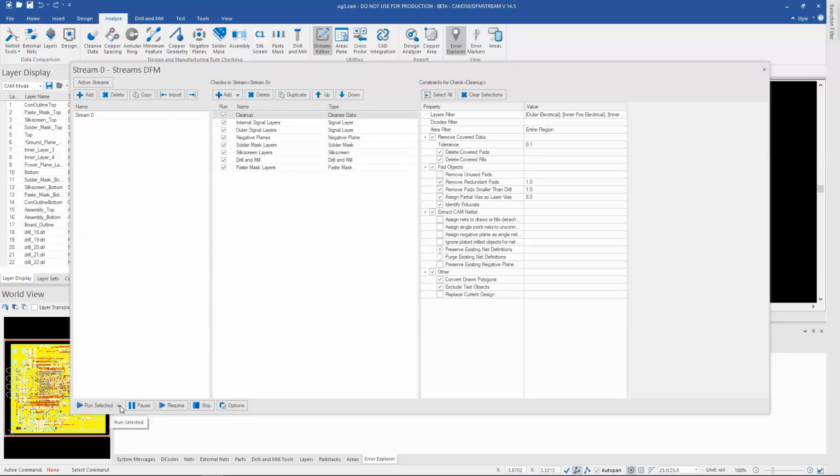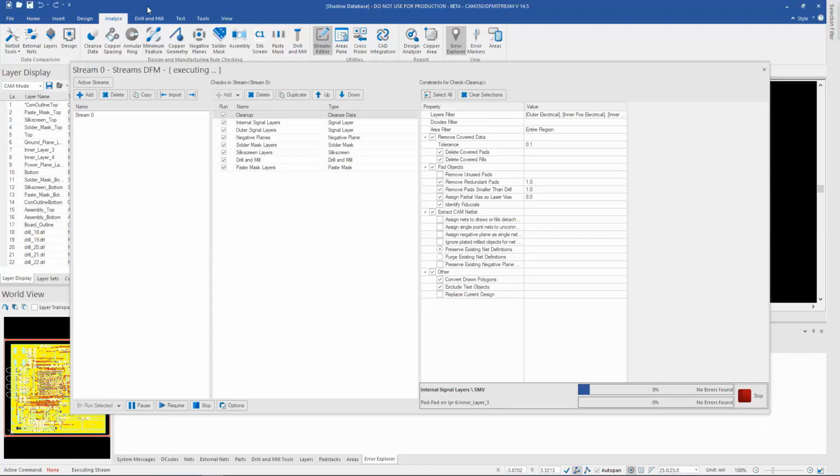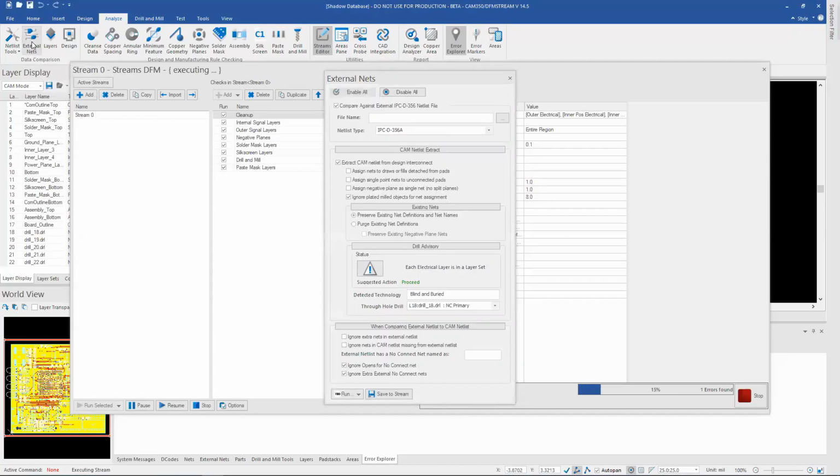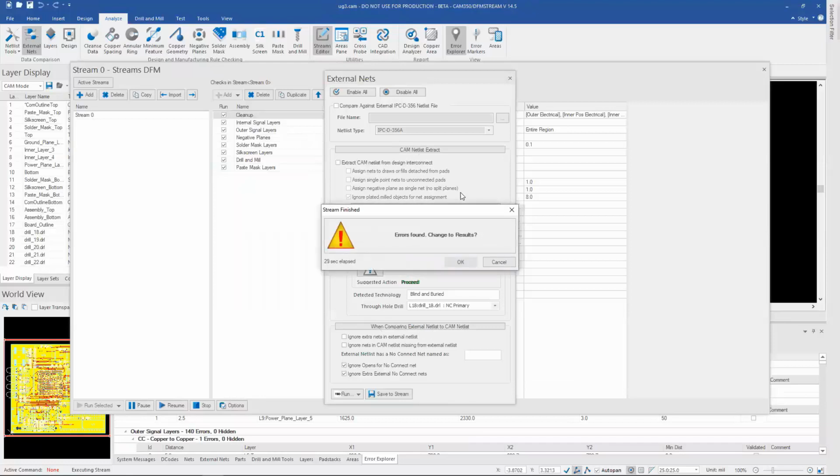I'm going to go ahead and kick it off, though, just so we run the analysis while I'm continuing to blabber on and on here. Because one of the things I wanted to show you is Netlist Compare, and I've mentioned this a few times already, that instead of jumping through various menus to do Netlist Compare, it's all right here. And as a matter of fact, if you walk through our standard loading process now, this is already done, and that's already done. So the only thing you need to do is compare your extracted netlist to your reference netlist.